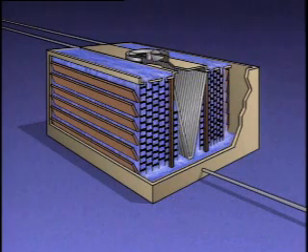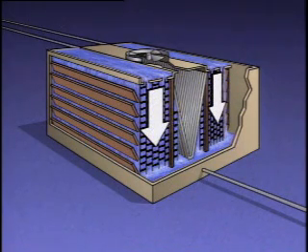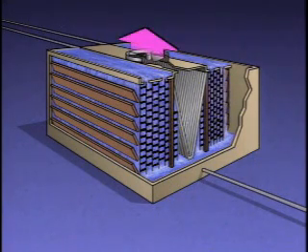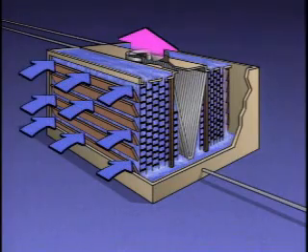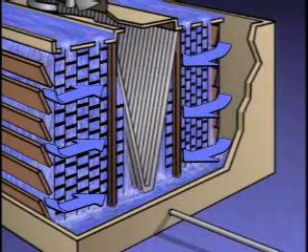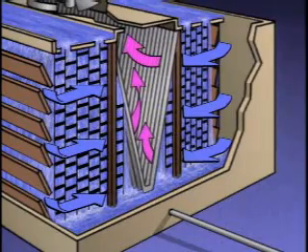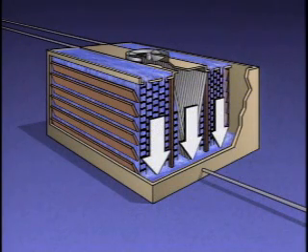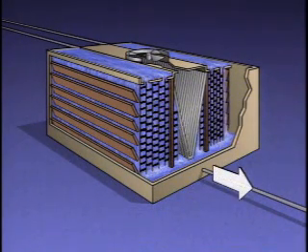As the water cascades down through the tower across the layers of packing, a fan draws the air in through a set of louvers, around the packing, and then through a drift eliminator. The drift eliminator traps water droplets that could be carried along with the air as it passes out of the tower. By the time the water reaches the catch basin, it's cooled. The cooled water is then drawn out of the tower through the outlet line and pumped back to plant equipment for reuse.